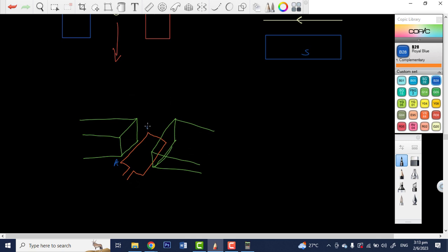So we're going to have A, let me just label this A, B, C, and D. Now we're going to have our, as I said before, split rings. So these are split rings right here, one on that side, one on that side. Then we're going to have our carbon brushes. So these are carbon brushes, and this now will be connected to a circuit, let's say like so. We will have a battery here, and maybe a little switch. Let me just close the switch.